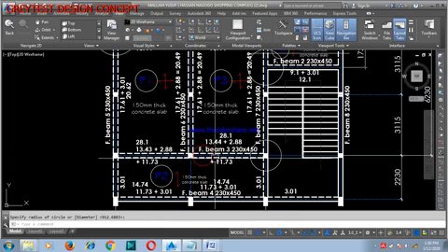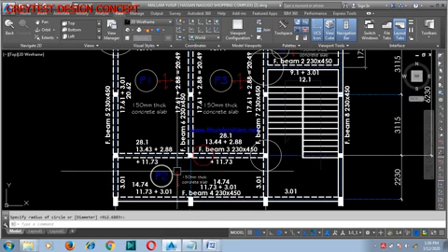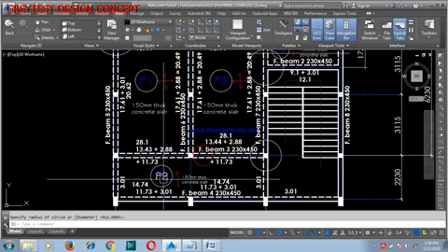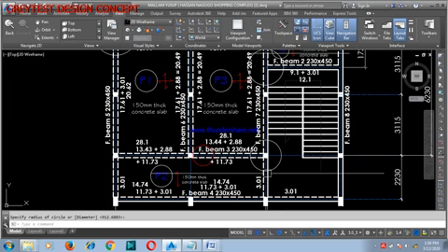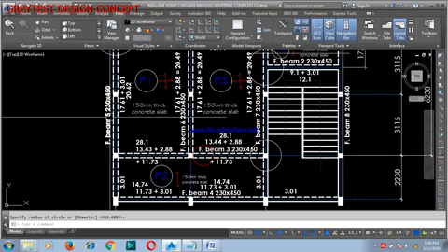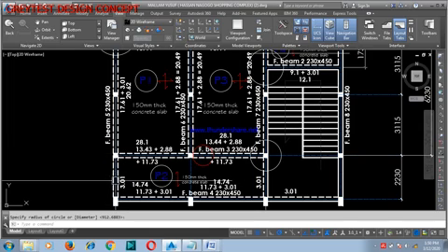This is your short span, right? Now this is the beam. Beam 3 and beam 4 are the beams actually carrying the load of this slab in panel 2. Beam 7 and beam 5 along this span are only carrying their self weight, which is 3.01. I'm coming to that. I will explain where we got 3.01 and 2.88 from.